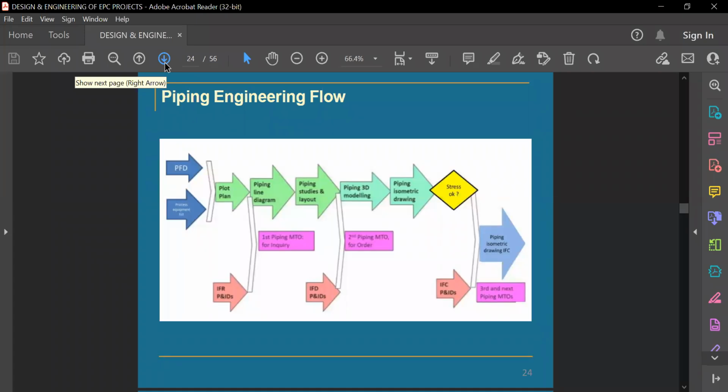or type of the valve, if you mention it, and then there is software that will give the dimension, face-to-face dimension. So they will take those preliminary dimensions, and they will put that one, okay, this valve will come in this pipeline, and this will be the pipe length and all those things, and then I can turn from here. But at the end, if the valve vendor document gives me, then I will give it to him, and they'll say, oh yeah, this is the final vendor drawing.